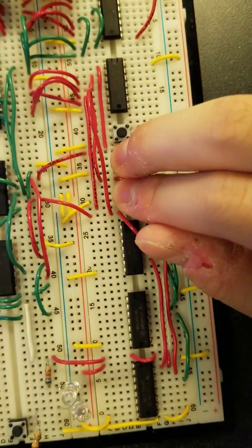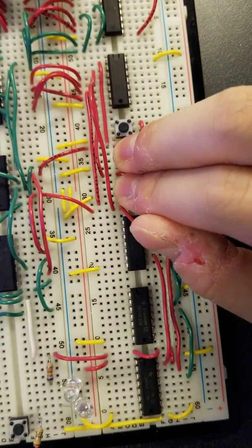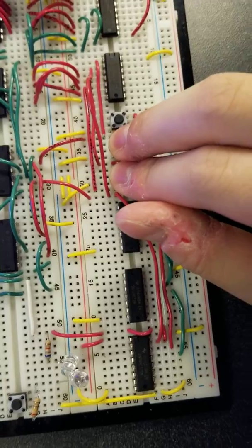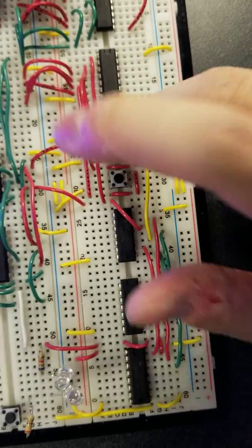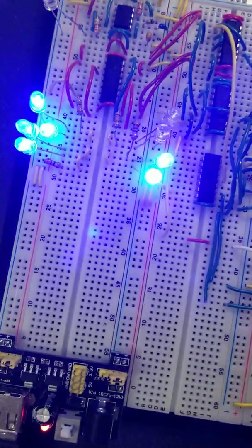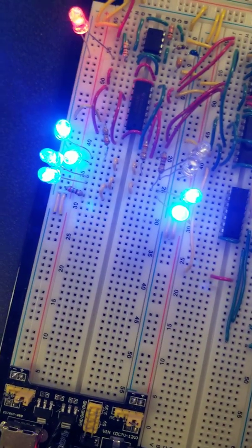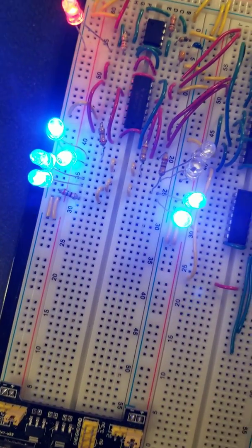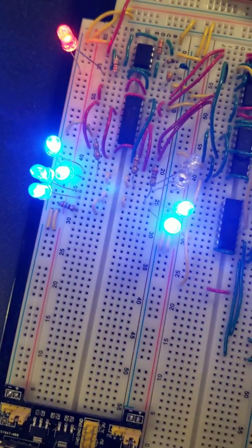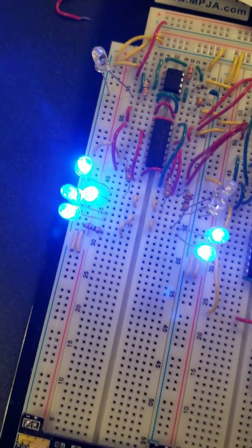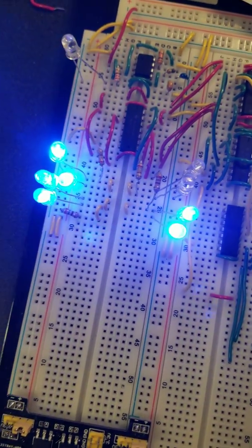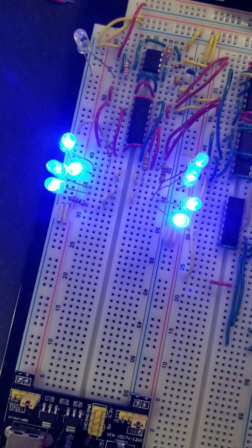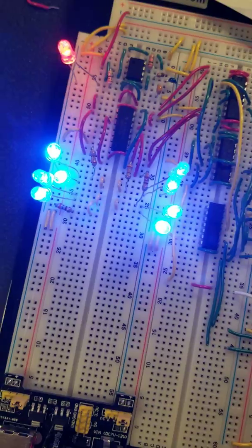Next, we want to test the left state. So when the track is bending towards the left, P56 is going to become 1, because P56 will be off the line. So we let go of that, and as you can see, the power becomes halved on the right side, and the power on the left stays at full power, suggesting that the tracker will end up moving more to the left side to keep up with the left bend. And likewise, you press the button again, and you get back to the straight state.